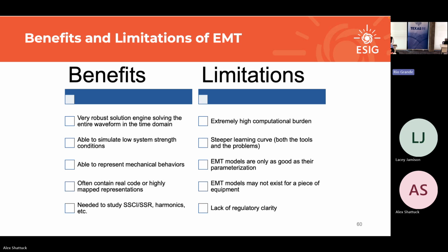So the benefits, which we've hit throughout: the EMT is a very robust solution engine. We're solving everything across the entire waveform. We're in the time domain. We know that domain, mentally. It's really good at low system strength conditions. Another benefit in the EMT is the level of detail, you can actually put mechanics in there, depending on how you build your models.